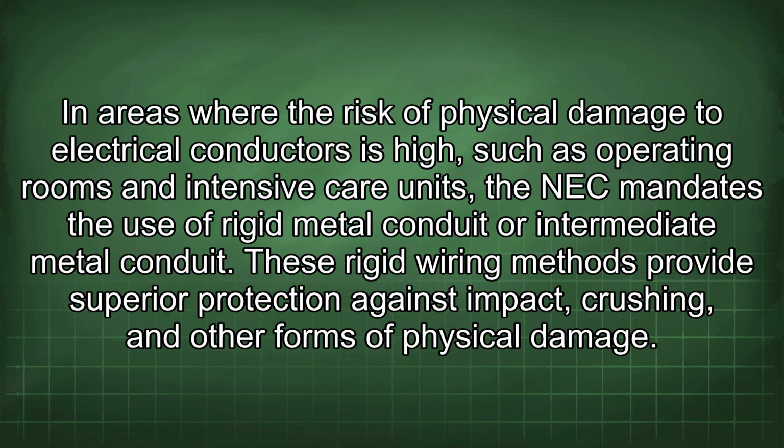In areas where the risk of physical damage to electrical conductors is high, such as operating rooms and intensive care units, the NEC mandates the use of rigid metal conduit or intermediate metal conduit. These rigid wiring methods provide superior protection against impact, crushing, and other forms of physical damage.